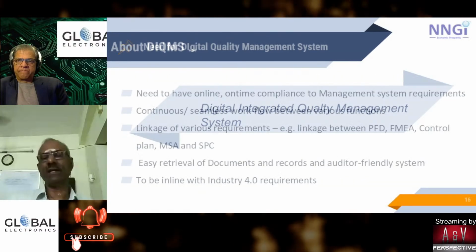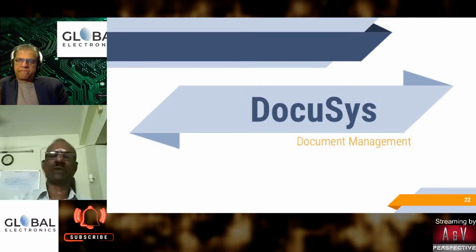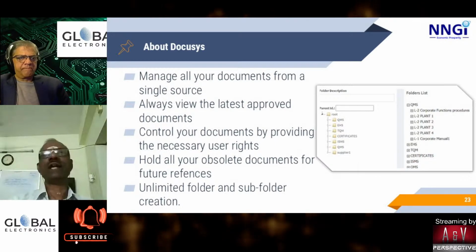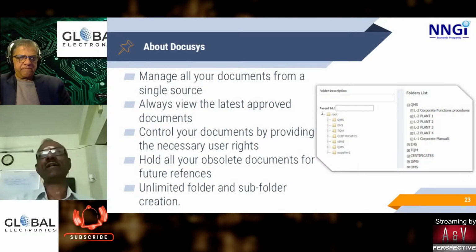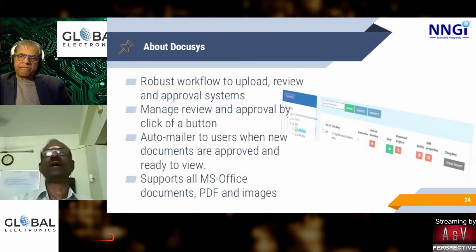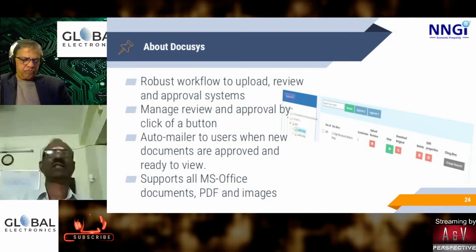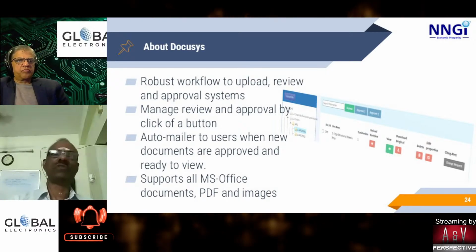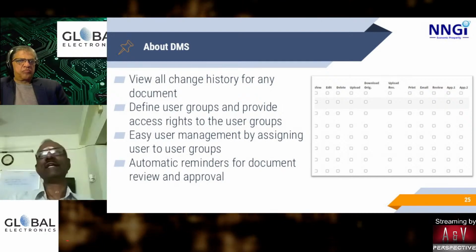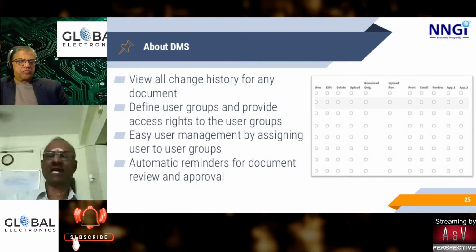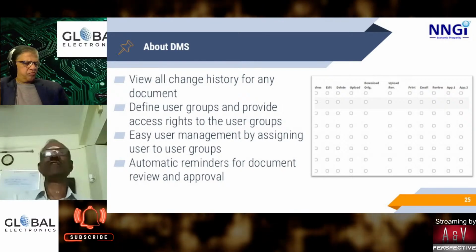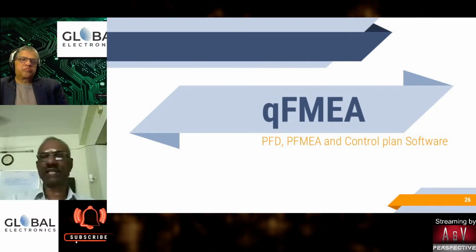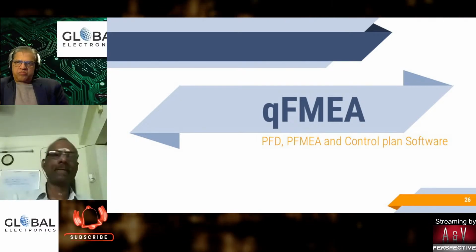And it has several MIS reports, which include failure mode versus cost matrix and failure causes versus detection matrix, which is very, very important for an electronics manufacturing industry. Various defects happen. This gives a very good database of what the failure modes versus causes are. For each type of cause, what is the prevention control? And for each type of failure mode, what is the detection control available? And it also prioritizes the list of higher severity failure modes, and also gives a priority for the action priority. Today the FMEA module works with the action priority table, that is also done.